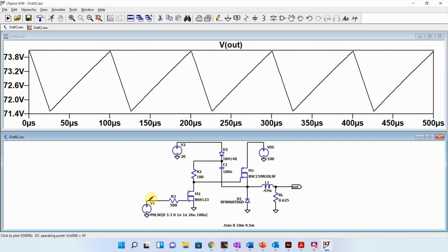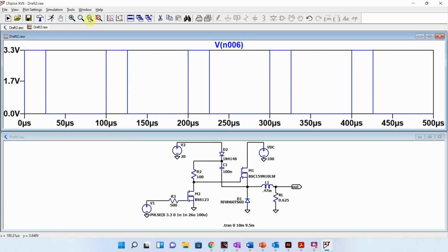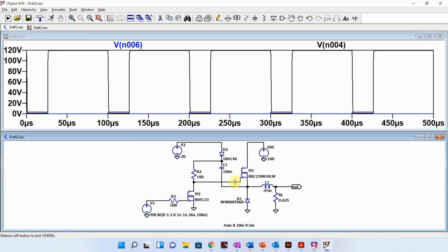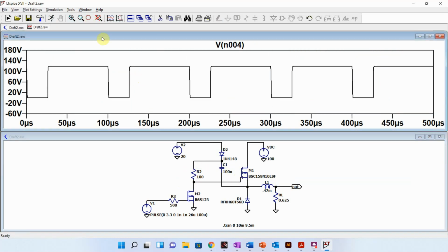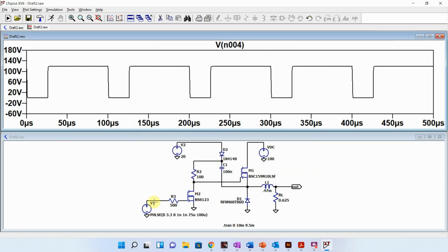Well, if I look through here, this one is 25%. But then if I look right here, this one is 75. So this bootstrap is inverting. So I'm going to have to come in here and make this one 75 micro rather than 25 to take into account the inverting of my bootstrap circuit.